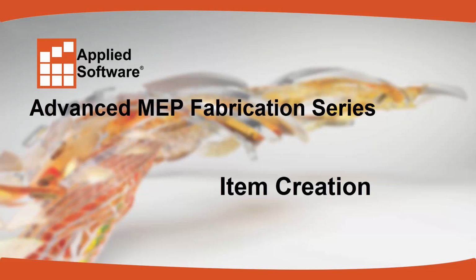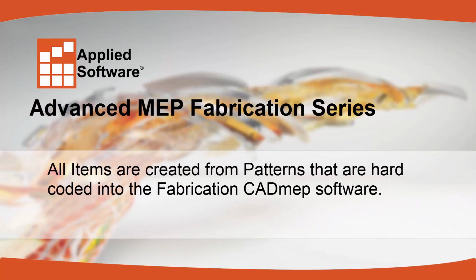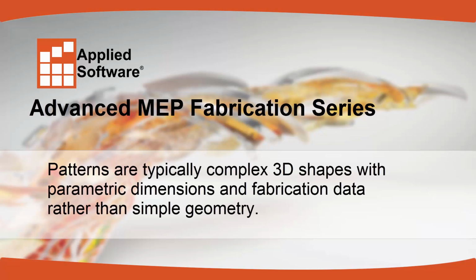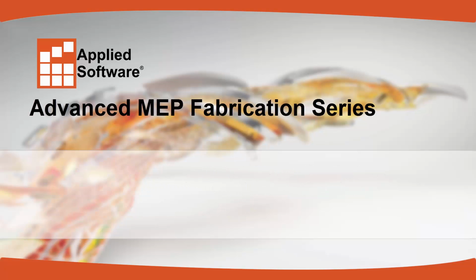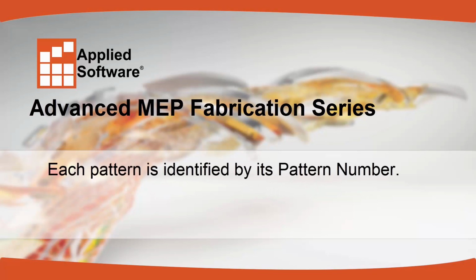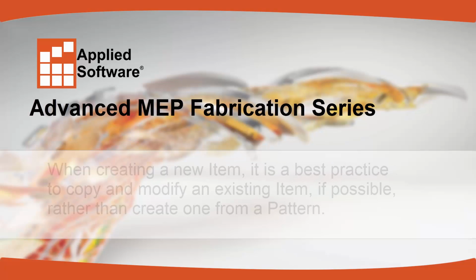Item creation. All items are created from patterns that are hard-coded into the Fabrication CAD-MEP software. Patterns are the basic building blocks for all fabrication items. Patterns are typically complex, 3D shapes with parametric dimensions and fabrication data rather than simple geometry. Only Autodesk can add new patterns, but the number and types of patterns in the software is extensive. Each pattern is identified by its pattern number.